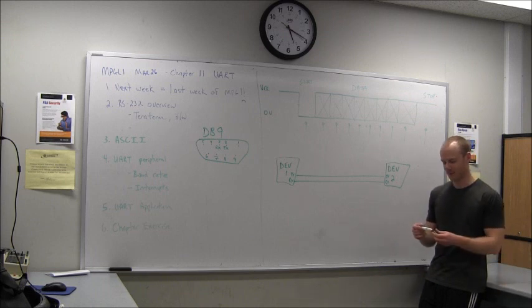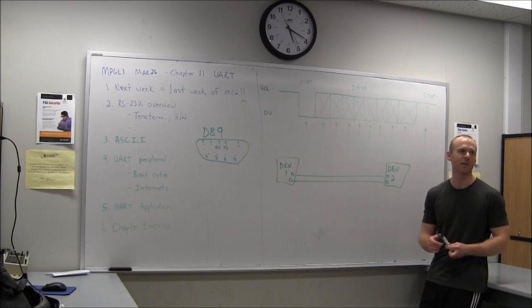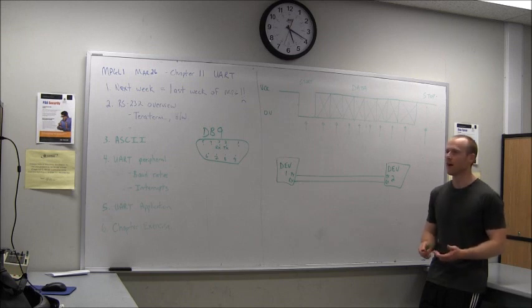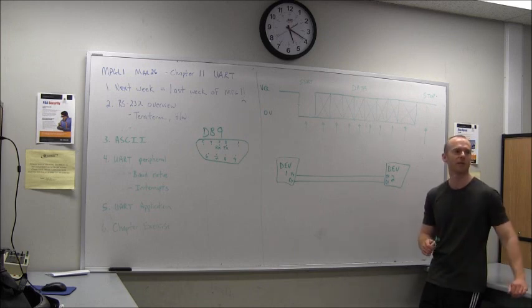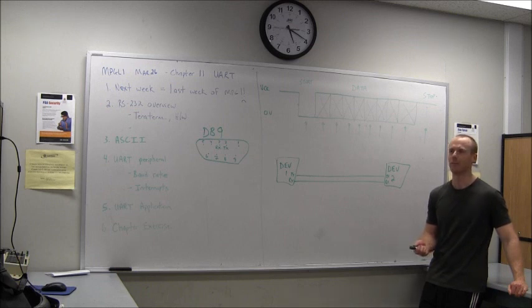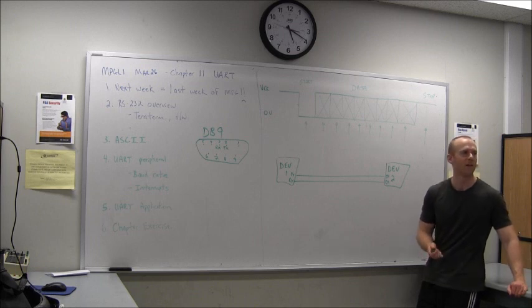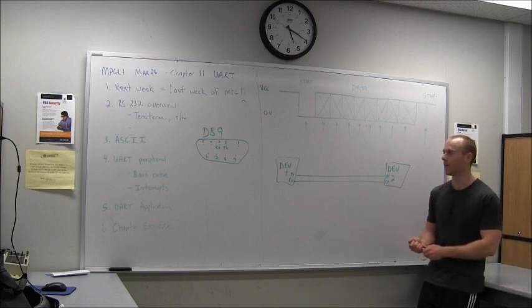So a very common baud rate is 9600, which is pretty slow. A faster one is 57600, and you can go up to, I think in Windows it says, about 115 kilobytes per second, which is pretty fast, and then you can do some higher speed UART speed. Because of the physical setup of this protocol, you're limited to a certain speed, so you probably can't do a megabit per second because the hardware isn't set up for that.